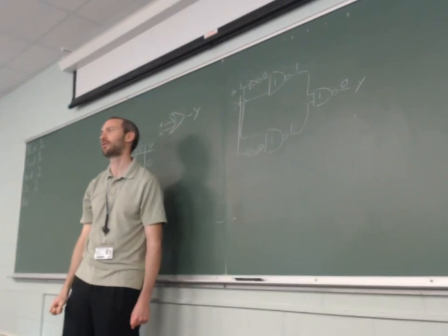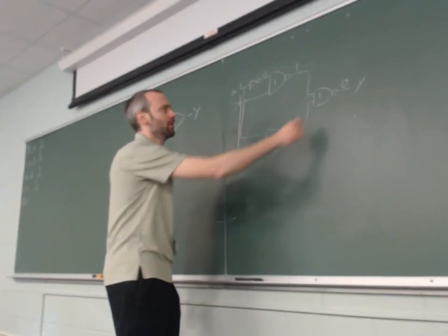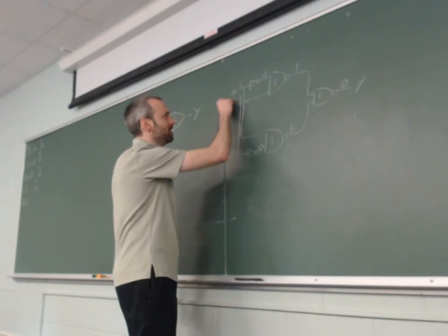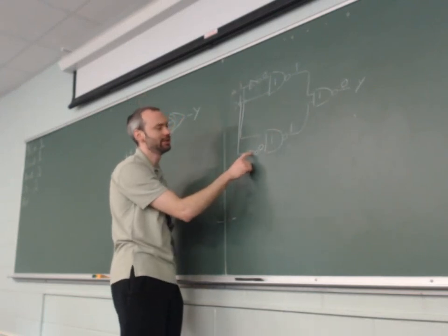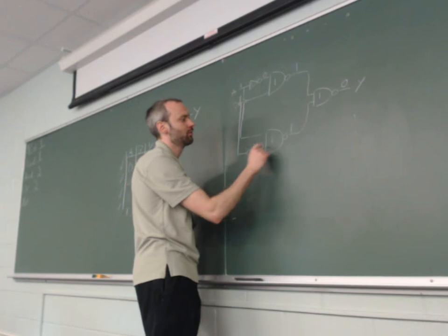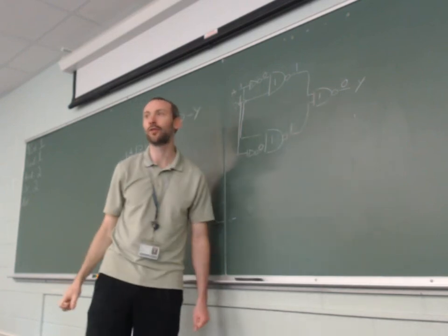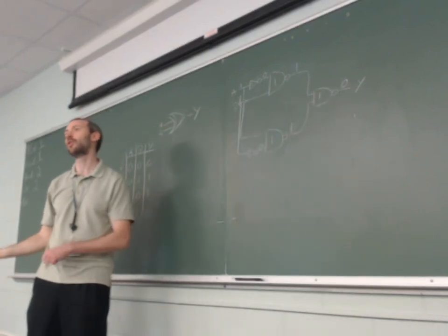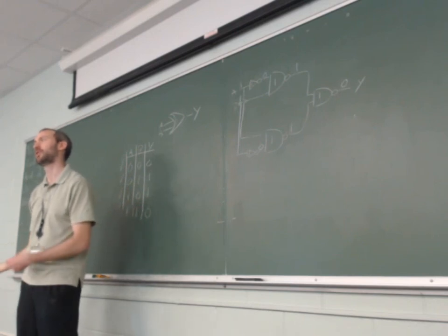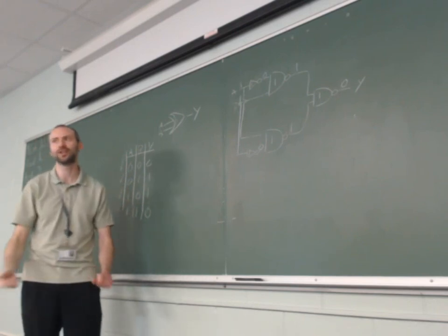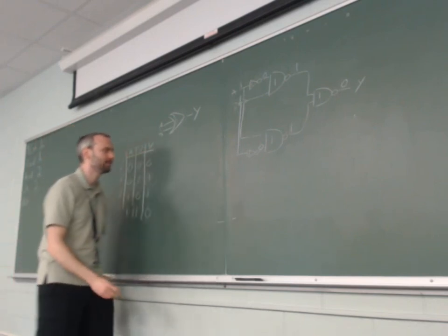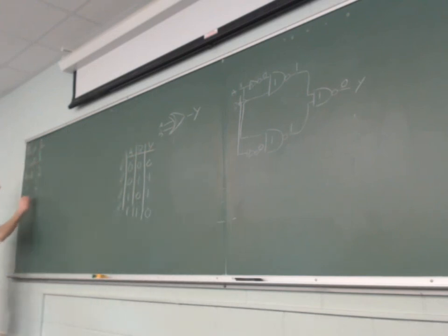What is the longest path? You could go 1, 1, and that would just be 2, but there's the inverter here, which takes 1, 2, 3 to get through. You always have to go with the longest path, because it could be the thing that changes everything. So in this case, we go with 3.